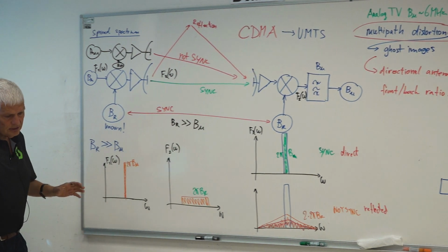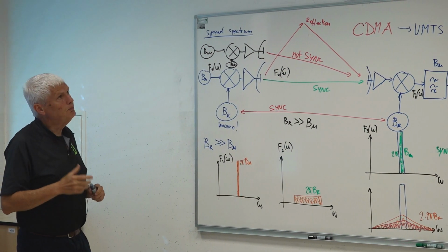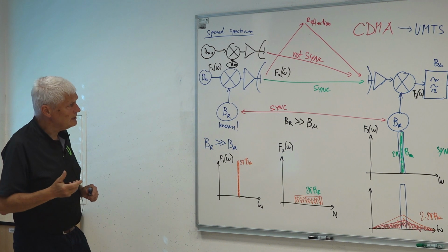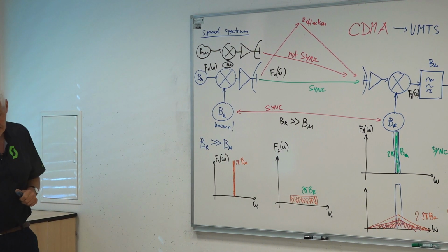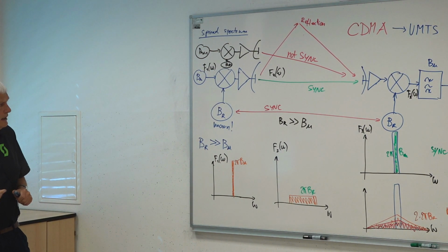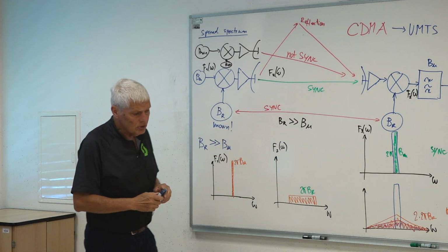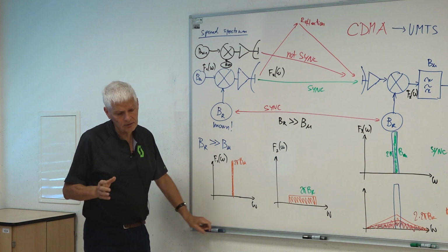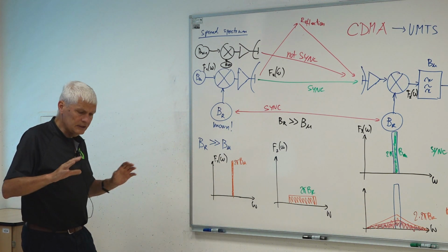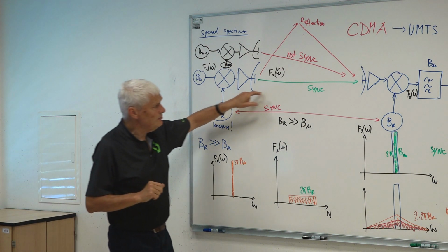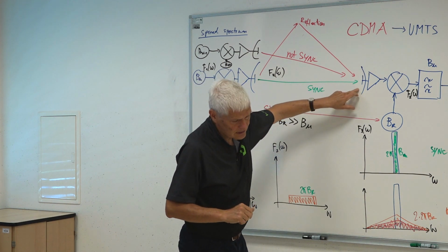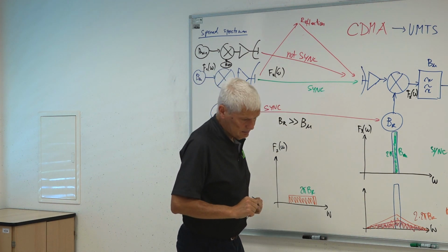We had to have all transmitters at the same power. And so power adjustment in UMTS and other code division multiple access systems was very critical, and quite a large part of the channel capacity was used just to control the power of the transmitters, to have all the transmitters adjusted for the same power at the receiving antenna.